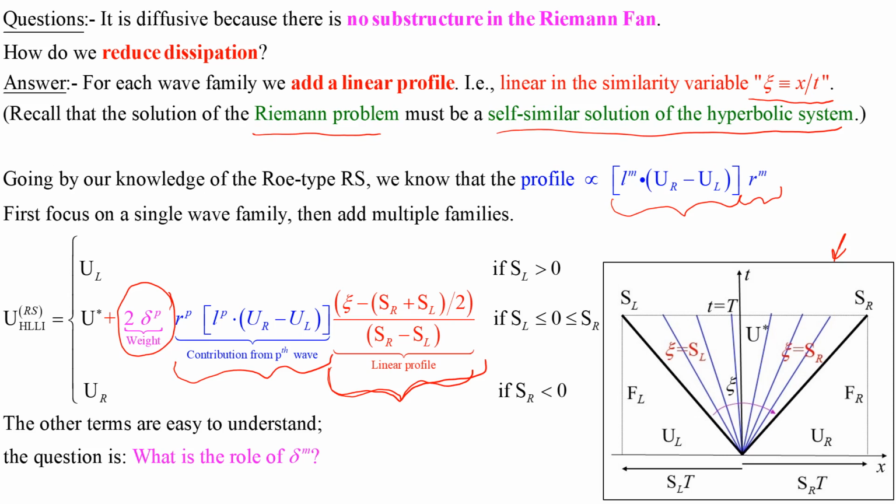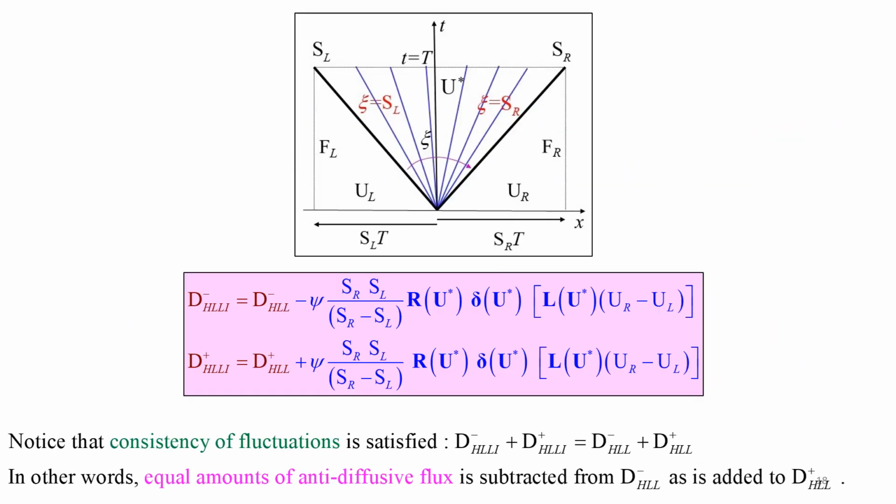It's basically carefully adjusted so that you put in not any more anti-diffusive flux than you should, because if you overdo it, then of course you will wind up with an unstable numerical scheme. So it gives you the maximum amount of anti-diffusive flux that you can put in while remaining safe. So it keeps you safe and it allows you to minimize the diffusion. So that secret sauce is carefully calibrated and it's documented in papers which we can point you to.